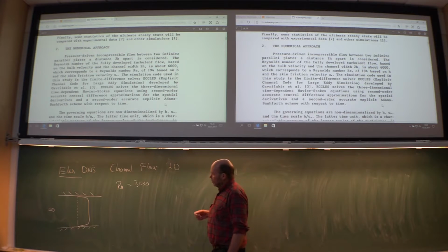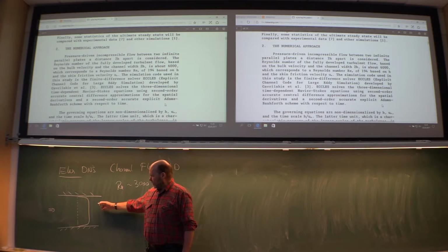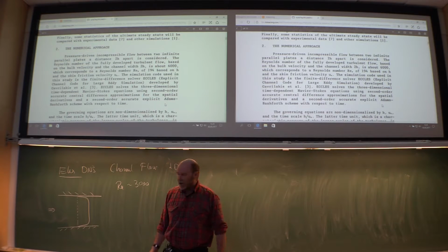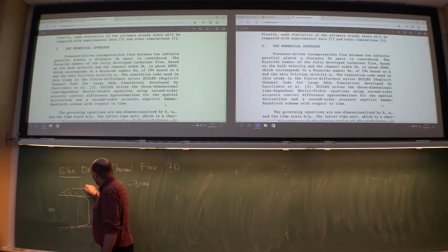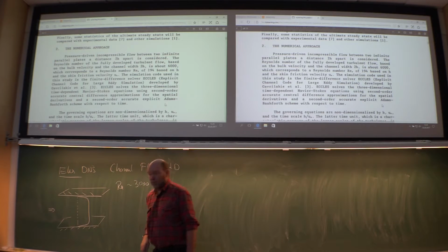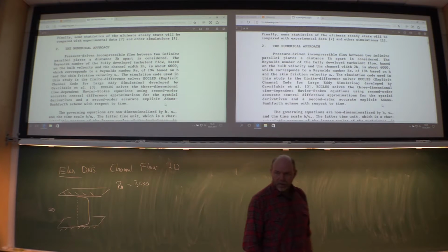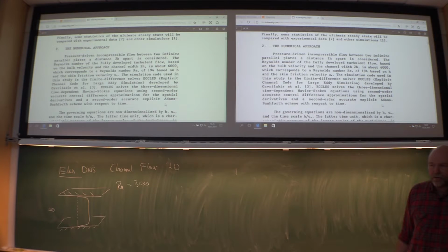And the reason that we then keep it so low, just turbulent, was just because of the resolution. Because for doing such a simulation, you still have to do it three-dimensional, like this. Although you're only interested in a one-dimensional solution, you still have to simulate a three-dimensional case. Because turbulence by nature is three-dimensional. And it's transient.